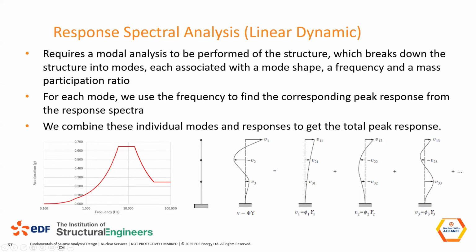Then on to response spectrum analysis. If you remember when we talked about the equivalent static, it's a similar kind of principle, but here we're actually calculating the modes that occur in the structure. Each mode will have a mass associated with it, and we can then apply an acceleration to that mass and then combine them all at the end.